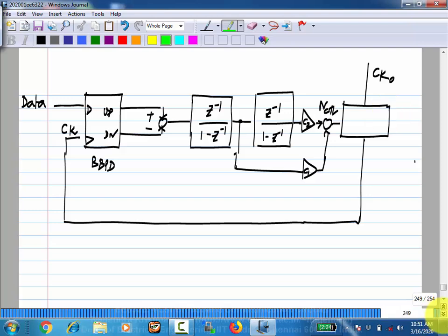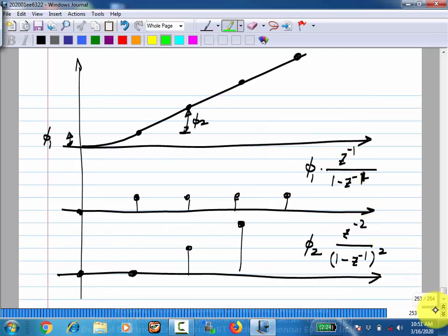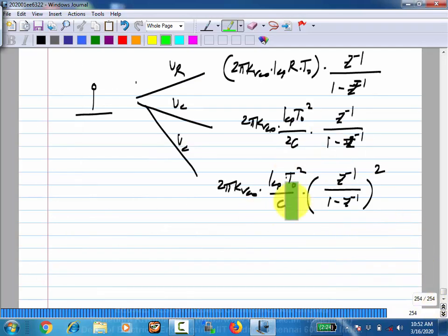And from this, I think now you have already done the assignment, right? So you can calculate the magnitudes of these different things to see what the LSB should be, etc. Okay. Finally, if the LSB comes out to be too small, you don't try to implement that, but you just live with a larger LSB and then do some quantization. It introduces some more errors. That's all. Okay. Please think about this. The digital CDR without the forwarded clock needs, just like in the other case, a proportional and integral path. We need an integrator to follow the phase and then another integrator to follow the frequency error.